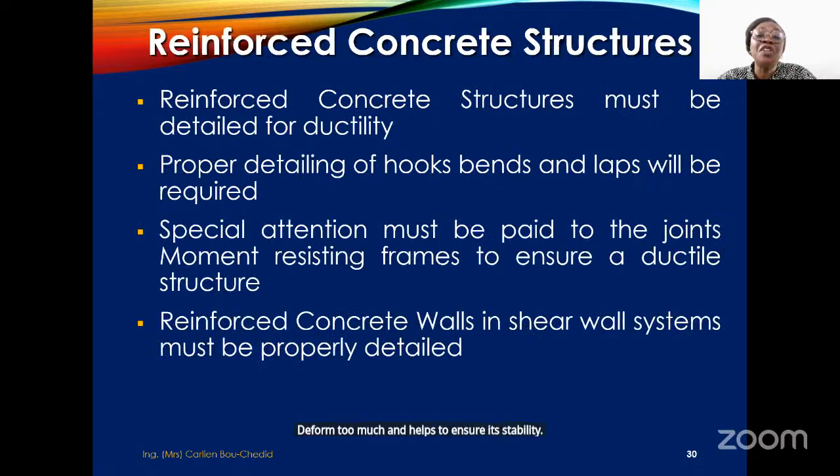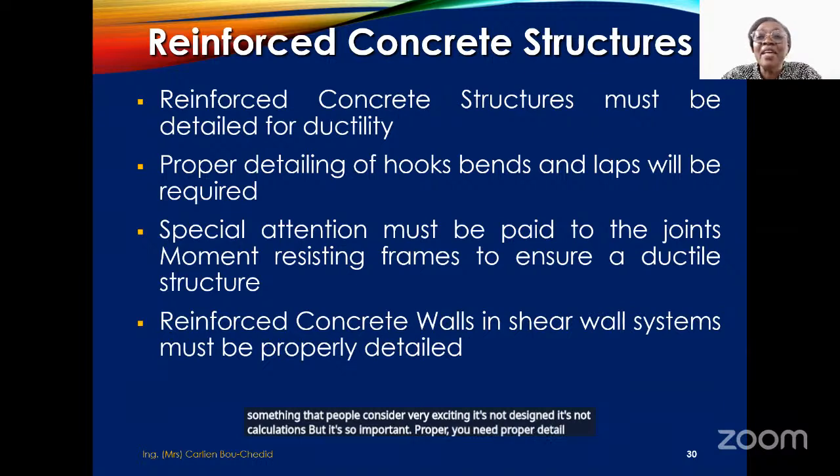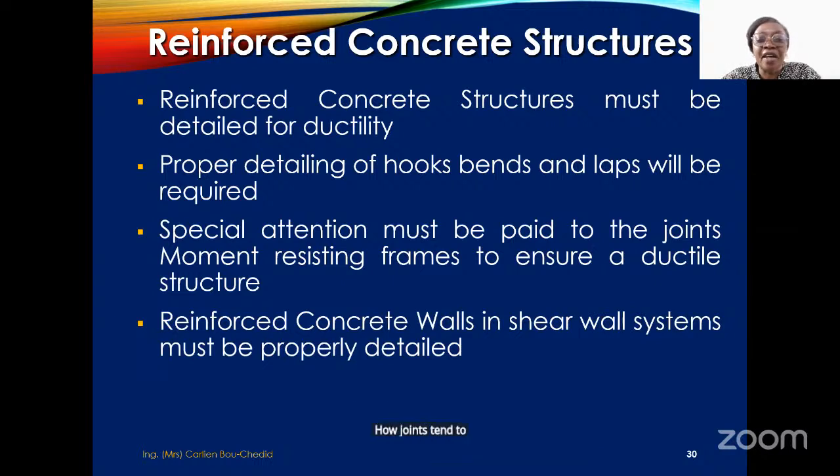With reinforced concrete, you need to pay attention to detailing. This is not something that people consider very exciting. It's not design, it's not calculations, but it's so important. You need proper detailing of your hooks, bends, laps, and so on. And you need to pay special attention to the joints. We've seen how joints tend to fail in earthquakes.